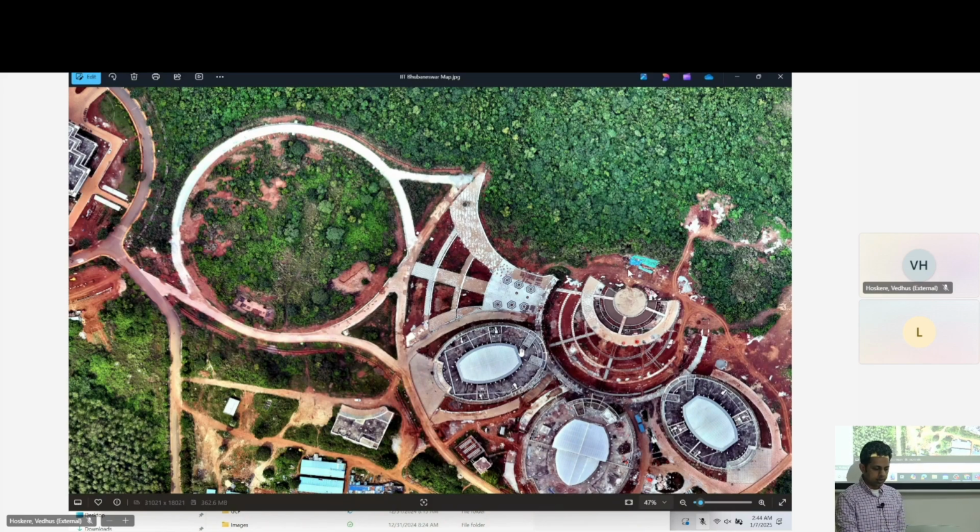If we're doing the overall structure, then we can fly even higher than that because we will still get a reasonable model. Then we need to decide the angle at which the gimbal is going to be for the different hatches. I would recommend having an oblique view so we can see some parts of the elevation as well.